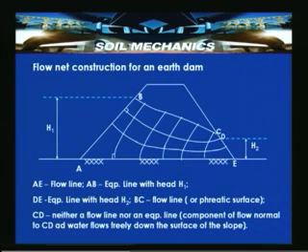If you look here, there is a component of flow down the slope, and there is also flow normal to CD. So it is eligible from both points of view, as an equipotential line as well as a flow line. This type of discrepancy does exist at small locations, but many times it is required to keep the phreatic line within the dam, and for that some measures like chimney drains or rock toes are provided.